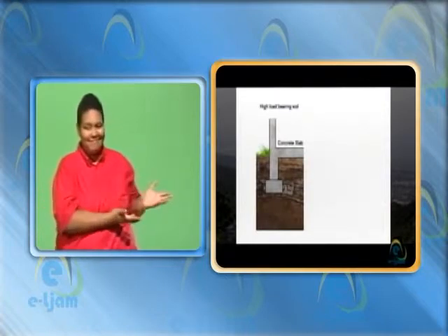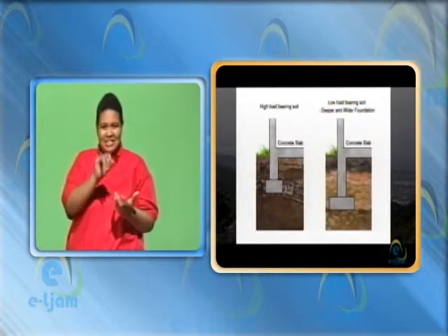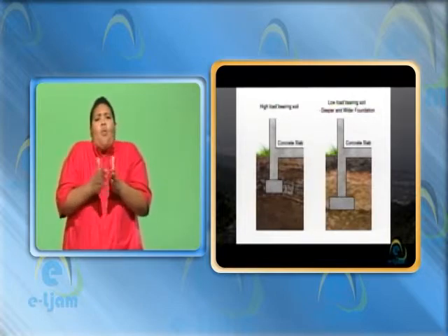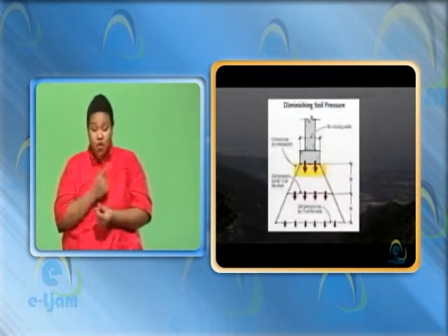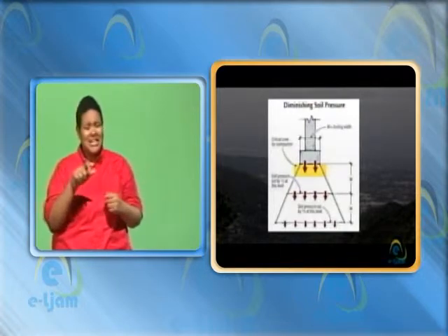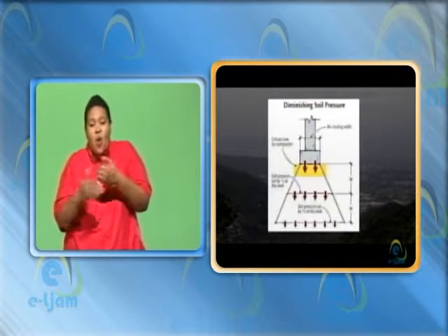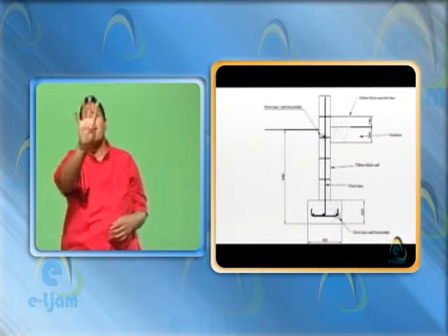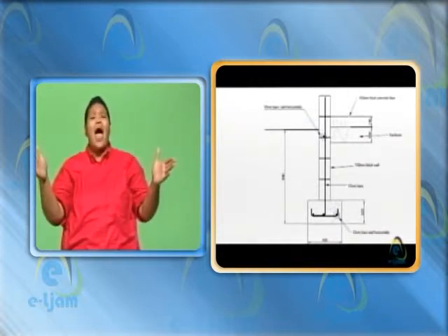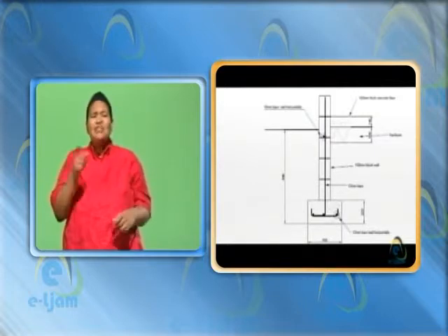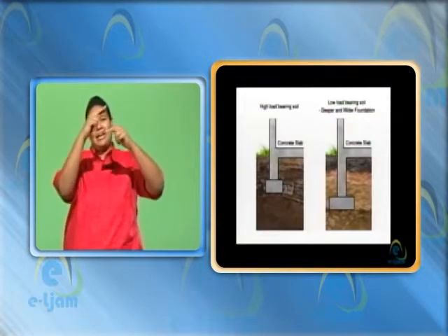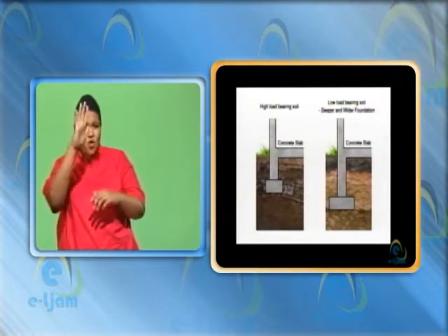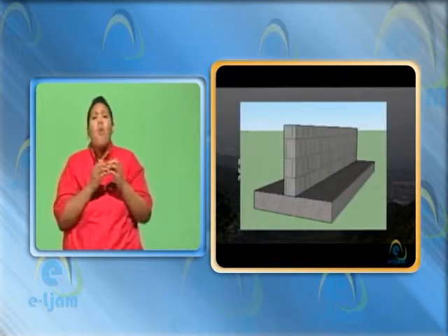So how does soil-bearing capacity relate to the size of the foundation? The lower the bearing capacity of the soil, the wider the foundation needs to be. If the soil is very strong, the foundation isn't even strictly necessary. Just the soil under the wall would be enough to hold the building up. For typical soil, a 400 millimeter or 600 millimeter wide footing can more than handle the relatively light weight of an ordinary structure. If you build on soft clay soil, or if there's a soft zone under part of your foundation, you might need a much wider foundation.